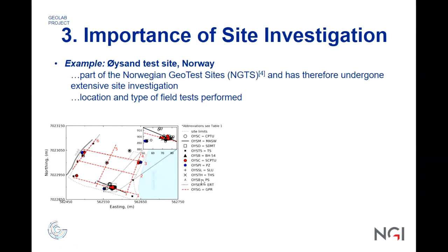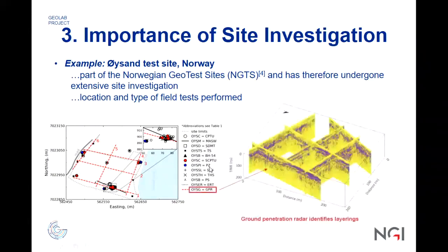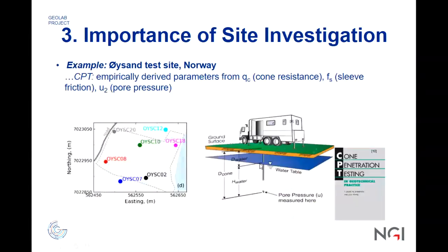As you can see here, this is just an example where we have performed different types of tests. And also a lot of tests are using geophysics methods to classify the soil between the boreholes, to fill in the information between the boreholes. We have also done various CPTs at this site. This is just an example of it. So we know the shear strength, both in drained and pore water conditions.